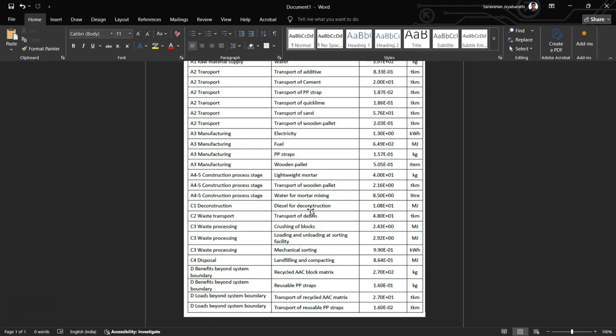Okay, I took 60%, because 40% goes as unsuitable in the process of recycling or crushing, right? So from the 500 kg, 60% only goes to the D module, right? So that the respective number has been calculated. Because so far we have the direct data with respect to A1, A2, A3, A4, A5, everything. Then once we enter into the C module, we refer to the data from the EPD, PCR. And for the D module, you should know the data, right? The numbers. That is how you come up with the number, right?